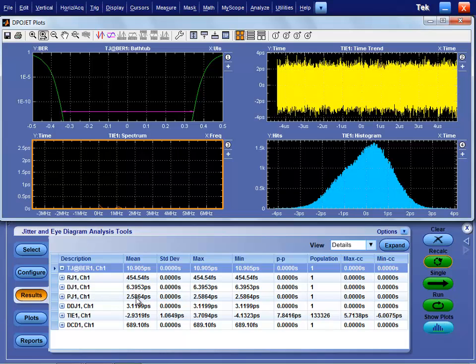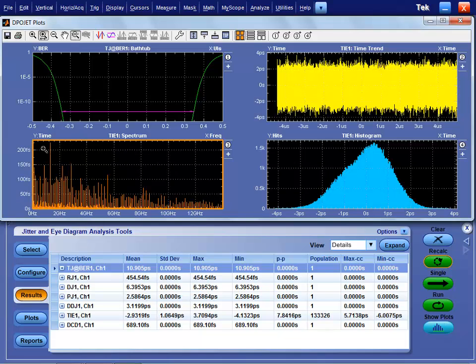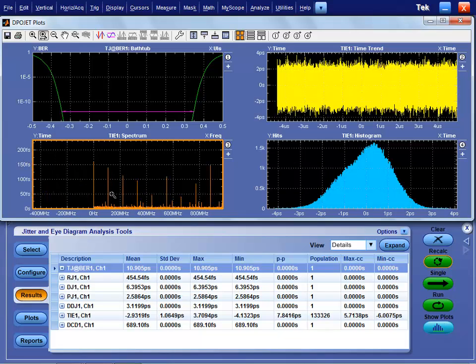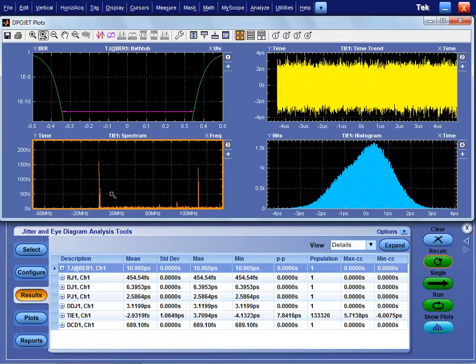and my periodic jitter is down from 10 to all the way down to 2.5. And notice in the time trend we don't see that modulation anymore. Let's go back to our spectrum plot and scale this back out. Now if we scale that to 100%, notice that my scale is no longer in the picoseconds on the sides. I'm down here in the low femtos, and there is some small things going on down here, but I don't have any distinct point driving that out. Let's go back and look at where that 1 megahertz was at. So remember, we had a 1 megahertz before.